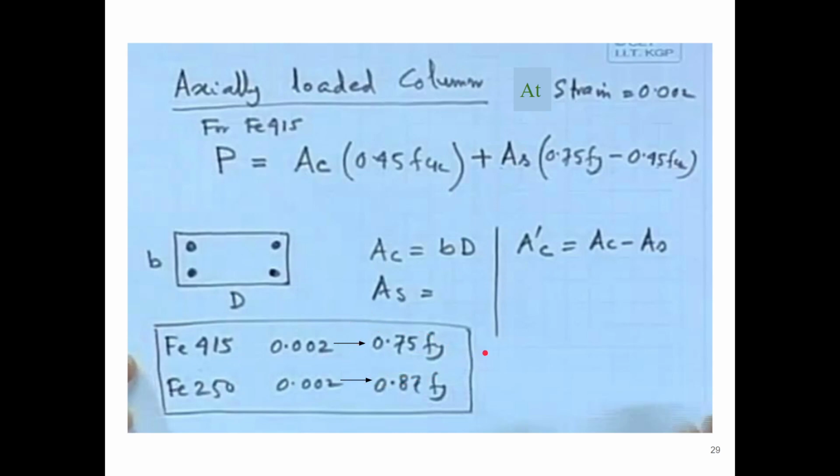Okay, so we are underestimating the capacity of the reinforcement bar for a better design, right? That is the concept of limit state design: to underestimate the capacity of the structure and overestimate the loading conditions. That's why we multiply loads by 1.5 and divide the material properties by the partial factor of safety.